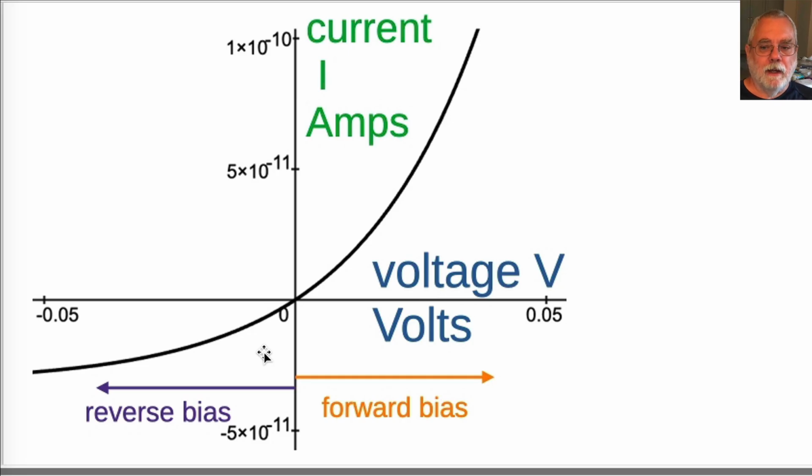This ordinary diode, not a photodiode, not a solar cell, only has operation in the upper right and lower left quadrants, where the sign of the current and voltage are the same in this convention for current. Power is current times voltage, paying attention to signs.